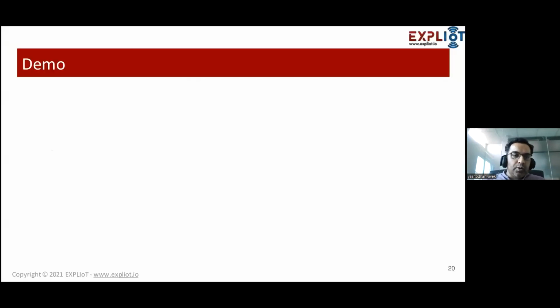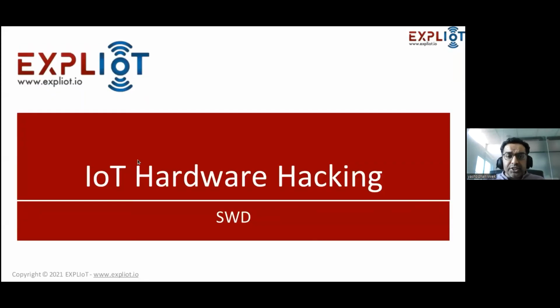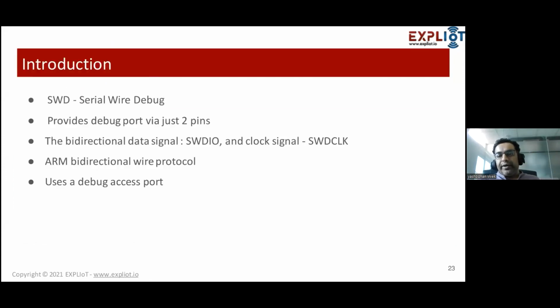Now let's go to our discussion on the SWD. Not much to go into on SWD, because the basic concepts have already been covered in the JTAG. To understand SWD, it is just one of the derivatives, where JTAG has n number of pins. But when you debug through serial wire debug, SWD again standing for serial wire debug, it is just a job of 2 pins over here.